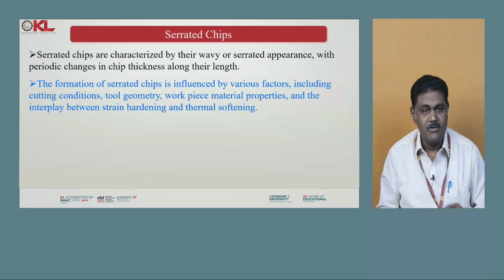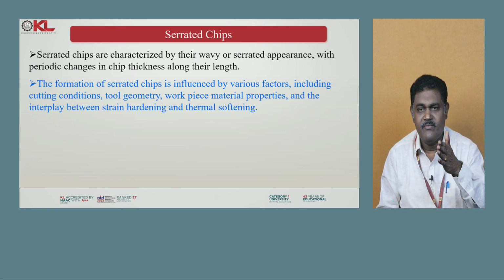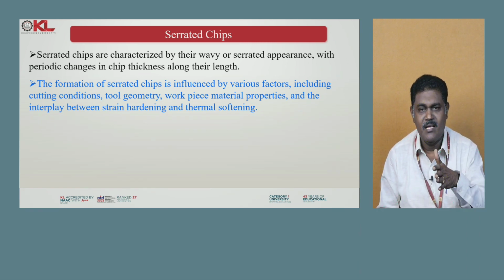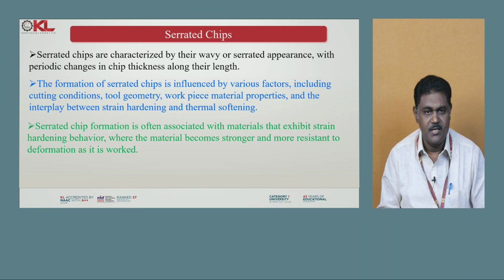So the formation of serrated chips is influenced by various factors including cutting conditions, tool geometry, workpiece material properties, and the interplay between strain hardening and thermal softening.